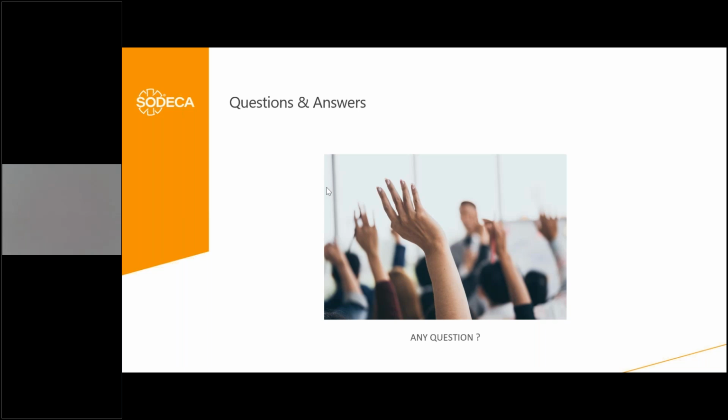Okay, next question. Can we use the elevator shaft as an air supply channel if it's in the same room as the stairwell? Well, difficult to say, Carlos. Theoretically, yes. It will be a possibility. But then I suppose you will need some grills between this elevator shaft and the staircase, because you cannot consider the leakage through the doors.